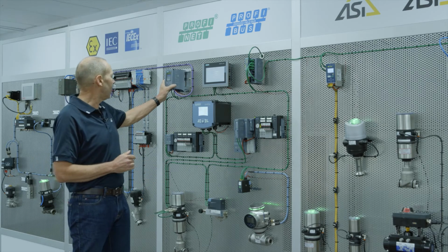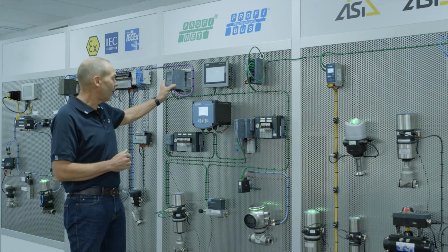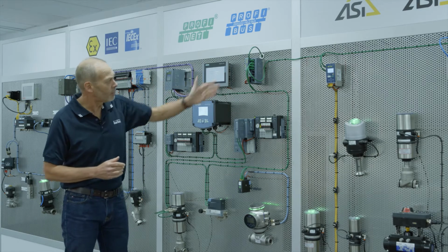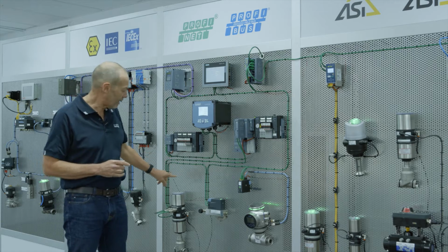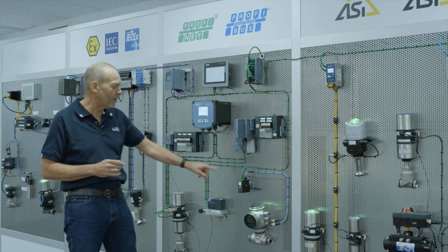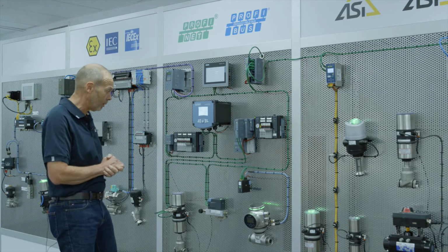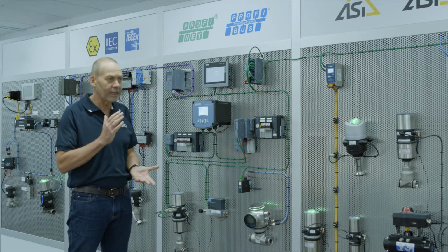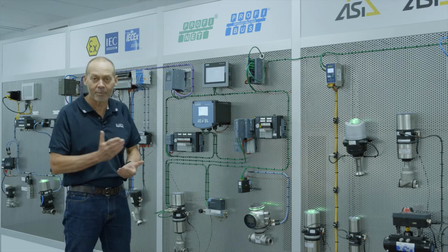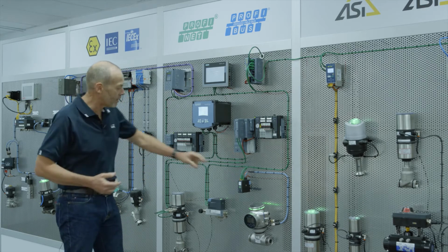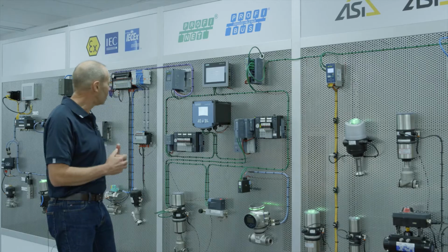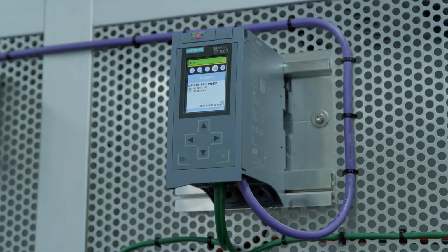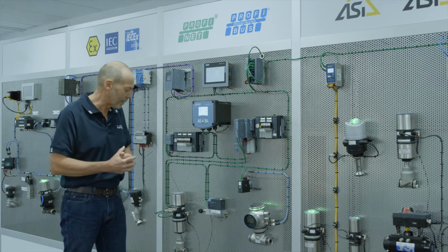So we're starting with a Siemens S7 PLC, and we've got a touch screen and also a managed switch. From there, we're setting up a redundant ring that goes around each of the devices installed here on the green cable. This redundant ring has the ability to accept a cable break and yet pick up immediately. I can demonstrate the operation of this by literally breaking the cable. Now you'll see that we get an alarm immediately that I've broken that cable, but it does come good immediately and says I'm back up and running.